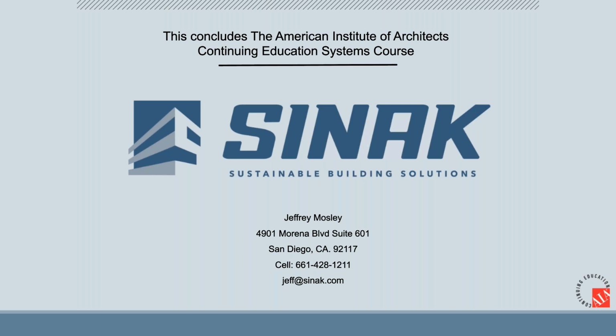Both of those are really good questions and very common. The ACI 302-1R15 put out a really good flow chart to help design professionals put the under slab retarders in the right place. It is kind of on a sliding scale, so there's not a definitive answer, but I will give you the best practices version that I have seen in my 30 plus years of doing this. If you're going to be dealing with flooring on top of your concrete, you always pour the concrete directly on the plastic or the poly. If you use a blotter layer, a sand layer, to take some of the moisture out, it stays trapped.